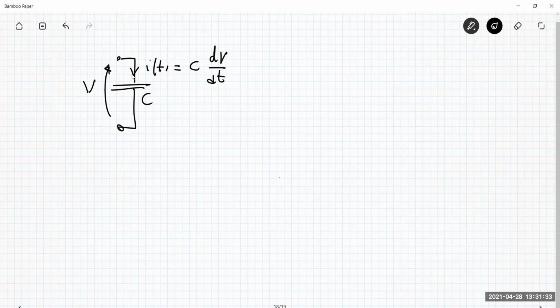This is what typically happens. So suppose that I want to consider a typical waveform of application. Remember what I said at the beginning: the voltage across these piezo actuators is better to be unipolar. It is better to have just, for example, positive voltage and not simultaneously positive and negative voltage, because if you apply negative voltage, especially if the voltage is very large, this negative voltage applied to the material can act as a depoling source, so it reduces the piezo effect.